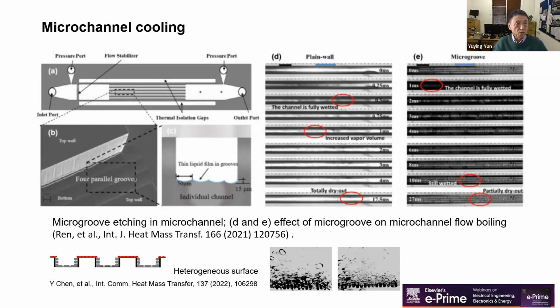The fabrication method of microchannels also needs improvement. The critical parameters for a microchannel heat sink, such as the material, size, flow channel layout, and microstructure placement, and also the general method of optimization design need to be further explored. Although nanofluids applied to microchannels could help to improve heat transfer, some research claims that after a certain period of working, the deposition of nanoparticles will be a problem. So the issue is there. They worry about the possible clogging of the microchannel, making it inefficient and resulting in overheating and damage to the devices. So it has to be considered.